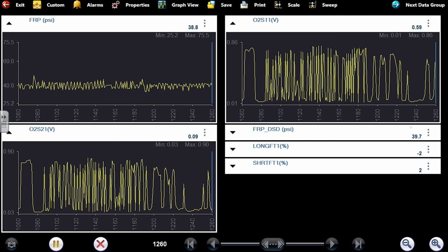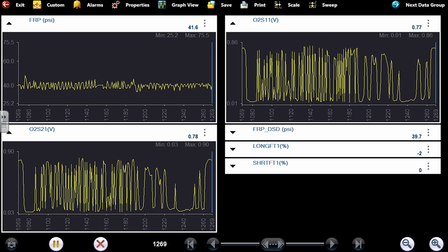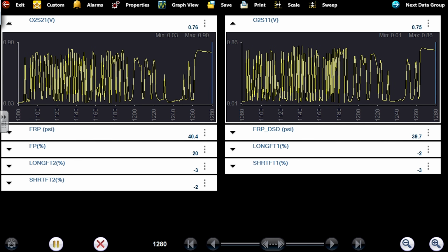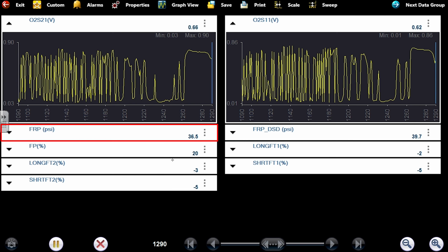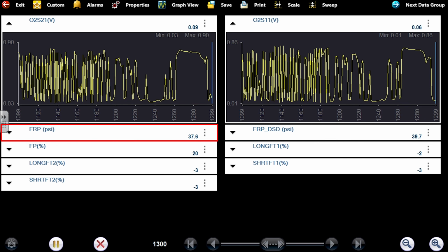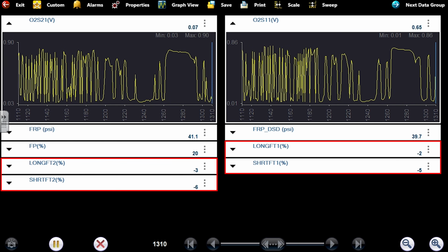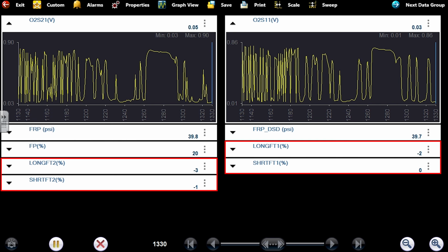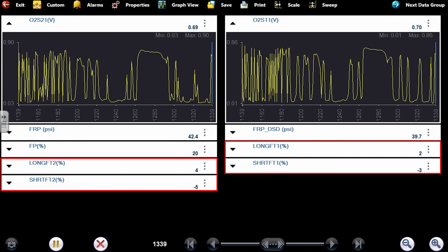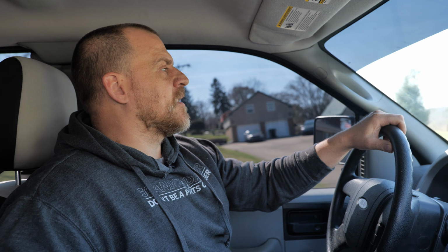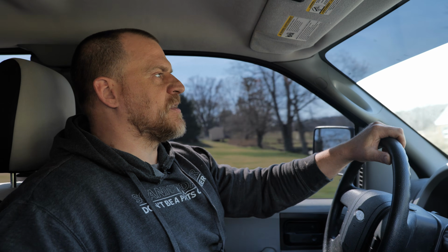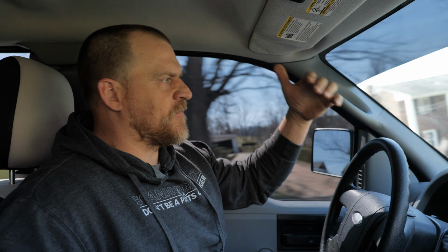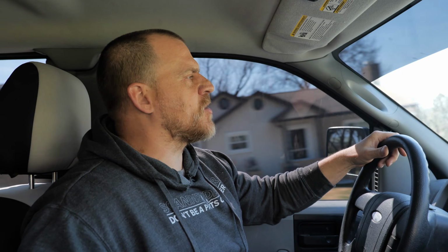Let's look at our trim numbers while we're waiting too. So let me ungraph that. My fuel rail pressure is now just digital right underneath the oxygen sensor. And then we can look at our trims. These trims look fine right now. I honestly am not worried about an over-fueling condition, even though we had rich conditions on bank 2. I just believe that is an effect of what was going on with this truck as far as the fuel rail pressure being out of range, the MAP and baro code, and the lean code. I think those three go together easily.